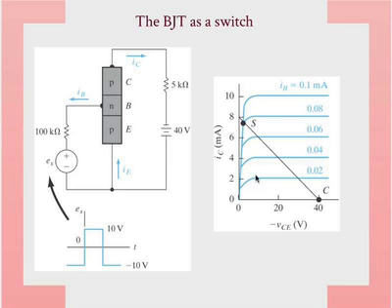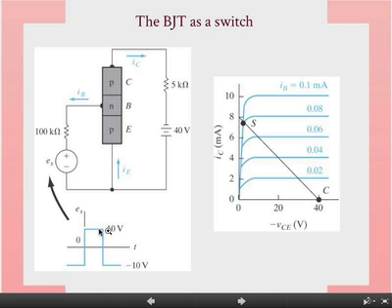Okay, we have curves which look like that, and each of those curves is controlled by the emitter current, which of course is controlled by the switch, whether it's forward biased or reverse biased. So going from a negative voltage to a positive voltage is akin to going from this point here, when it's positive voltage, it's reverse biased, to that point here. Zero current to very large current. Okay?